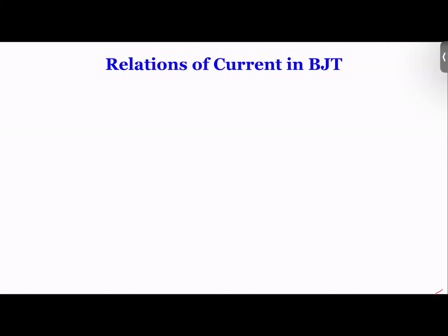Last week, we started BJTs. As you go through the homework on BJTs, it's very important that you distinguish the operation modes of BJTs from the operation modes of MOSFETs. If you remember correctly, in a MOSFET, we use saturation for the flat part of the current, but we use triode for the linear portion of the MOSFET operation.